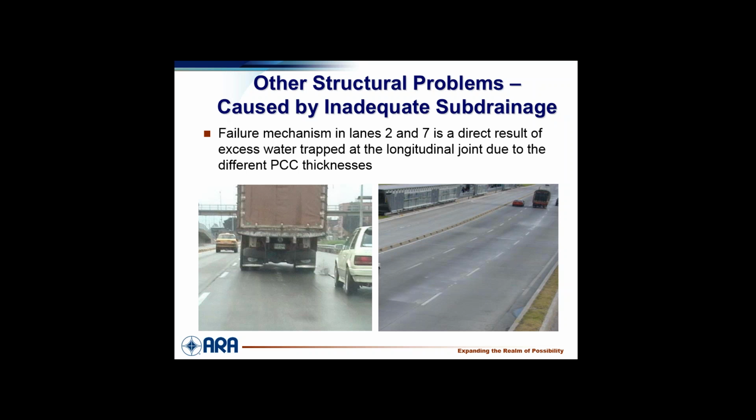A geyser, yeah. I was sitting in the Atlanta airport terminal one day, and a big plane pulled in, with a gear coming right down on a corner of a slab. Just as it got there, this geyser went up, just like this, and down. Literally a geyser of water came out of that pavement. There was so much water under that. And this is worse, because Barry Dempsey measured pressure under here, and it's pretty high pressure. That impact, that water hammer, I guess we would call it, is huge.